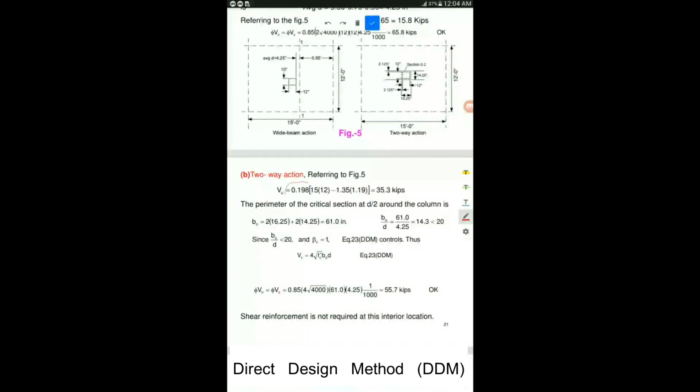So this is the floor load again here. You have to multiply this floor load, or the pressure area load, with an area which is lying outside this dotted line. So first you're going to multiply this 15 feet and 12 feet. You're going to get the total area, and from this total area you're going to subtract the inner side.